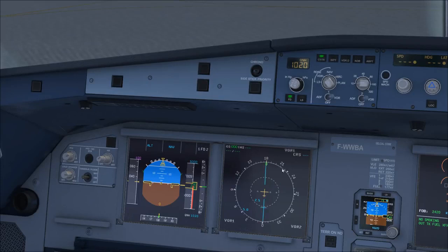You also have a VOR there, so you have like a digital VOR indicator. And then you've also got a landing system. So again, that's very similar to a horizontal situation indicator. However, this also gives you glide slope information as well.